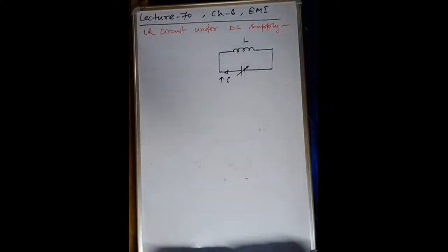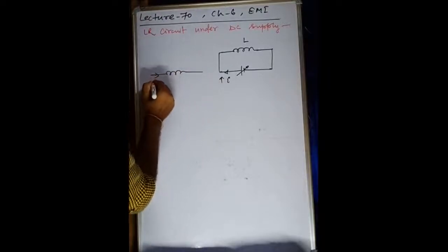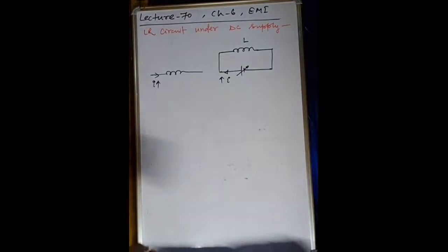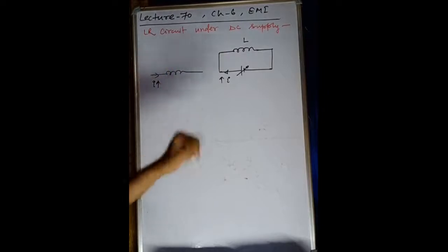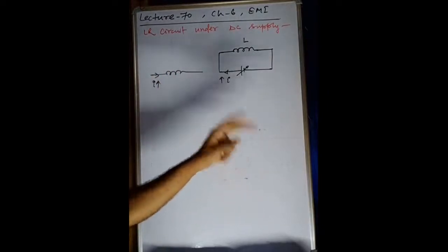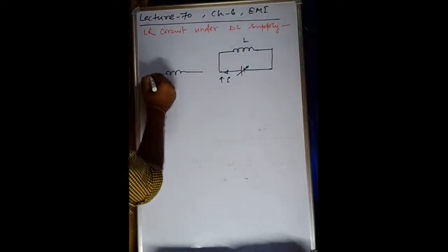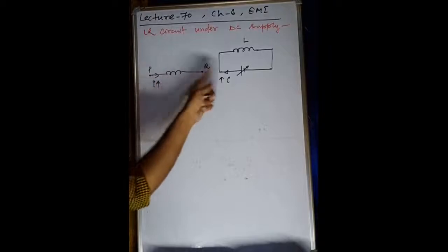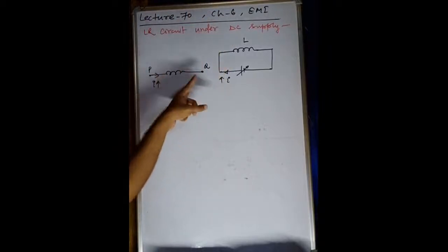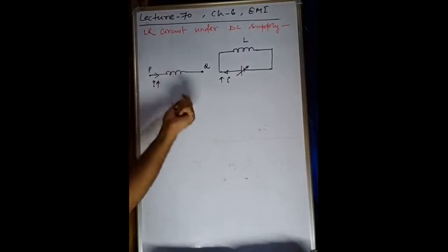What you have to suppose, listen carefully, although I have explained already, again I am telling you, if this is the inductor and current I is increasing in this direction, then you have to consider a cell on behalf of this inductor. This inductor will be considered as the cell, but you need two terminals, which will be positive and which will be negative, which will be at high potential and which at low potential. Suppose this is the point P and this is the point Q. If the current is increasing in this direction, tell me which point will be at high potential due to the back EMF?